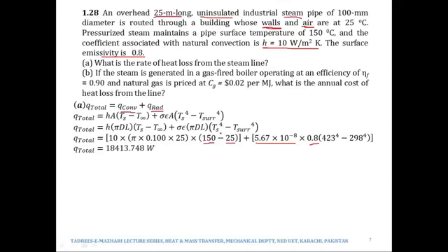now we are bound to put the temperatures in Kelvin if we are using radiation. See, in convection it is ΔT, but in radiation it is not ΔT. It is T1^4 minus T2^4. A ΔT in Celsius is the same as a ΔT in Kelvin, but the same is not true when it is not ΔT. So the same principle cannot be applied in case of radiation. Therefore over here we are bound to put the temperatures in Kelvin.